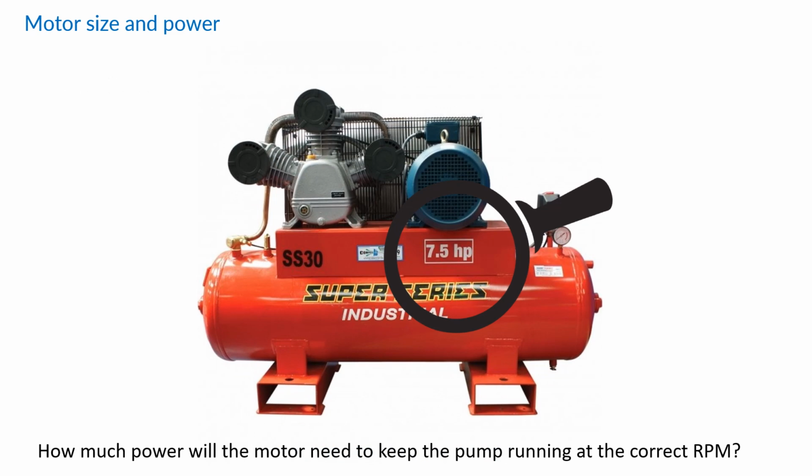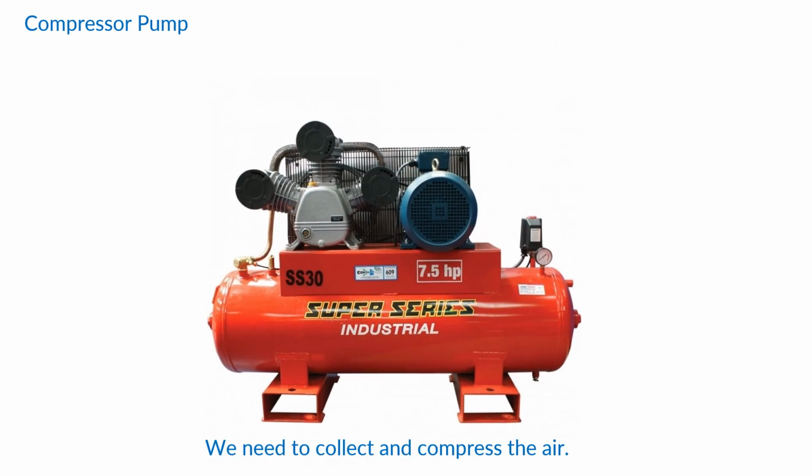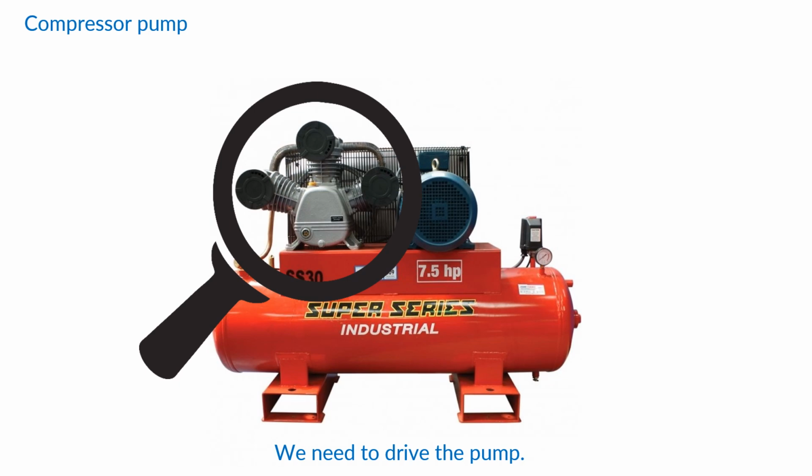The power required to drive the pump will be determined by the volume of air that we need to move and the pressure that we need to achieve. The compressor pump. Remember, pressure is resistance to flow, so we'll need an efficient pump and a powerful motor if we're dealing with high pressures. Charts, tables, and apps for sizing compressors can be found on compressor manufacturers' websites and technical documentation.